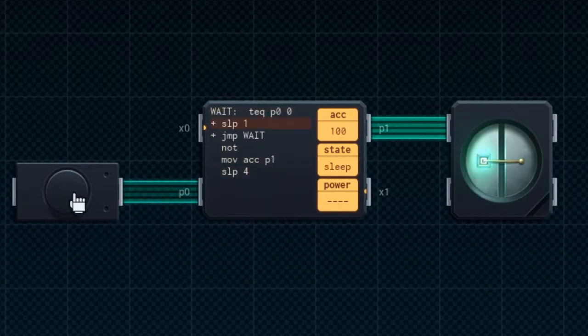So let's run the simulation. We press the button, and now, yeah, as long as we keep giving it proper clicks, it doesn't fail. It won't ever fail. So this is a good and interesting solution. But if we hold the button, it starts blinking, which is not exactly what we want. Maybe we want this, maybe we don't want this. But yeah, I would say that for a T flip-flop, this is not desirable behavior.